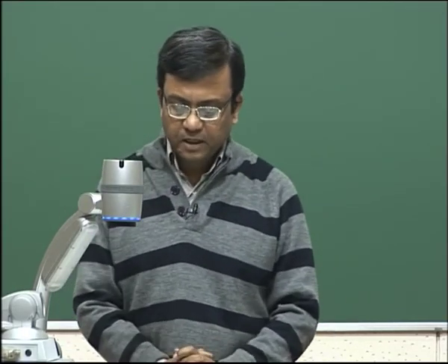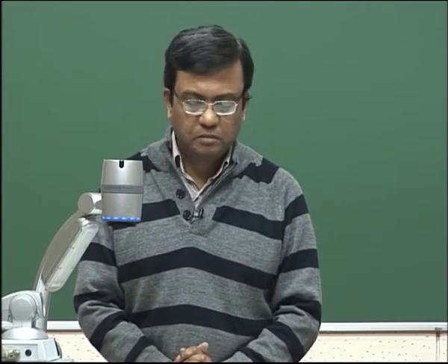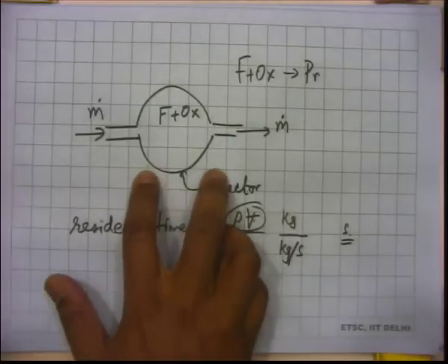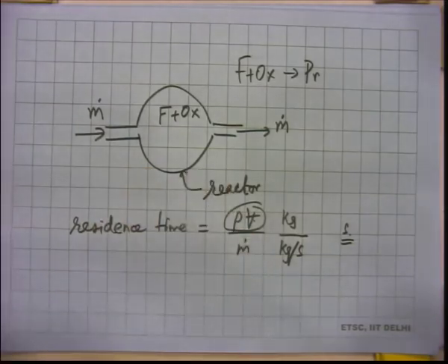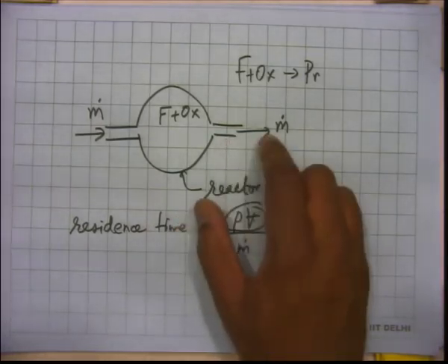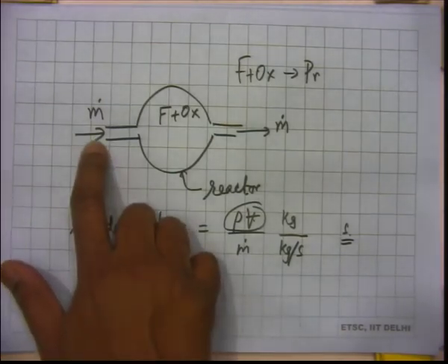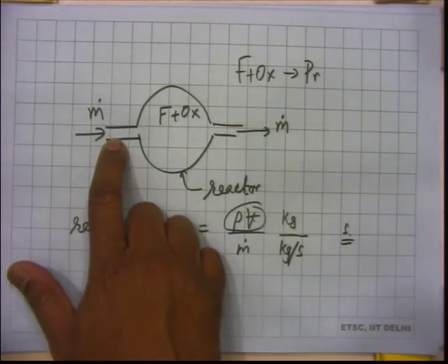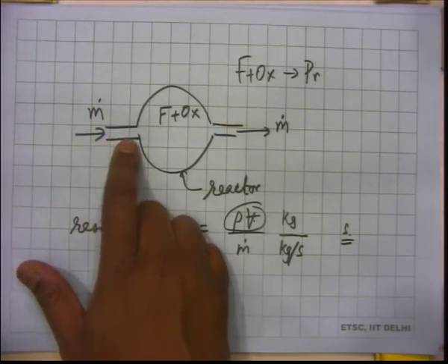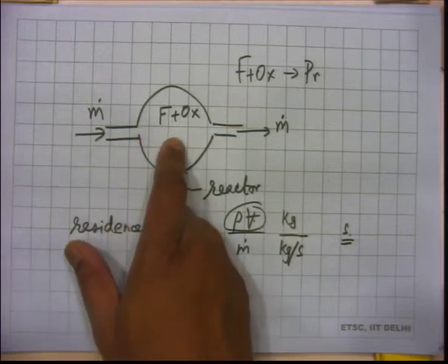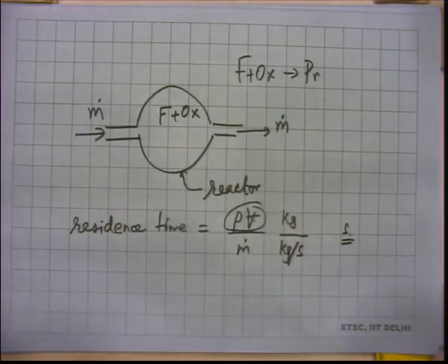So, if you have, let us say, a gas turbine, conceptually something similar to this, because you are sending fuel and air mixture to the gas turbine and combustion takes place. Combustion products go out and then they will go and run the turbine. Okay. So, imagine what will happen if you try to push the fuel and oxidizer too fast through the turbine. Then they may not react, and if they do not react, then you do not get these hot gases which will go and run the turbine. So, you will get into trouble, isn't it?